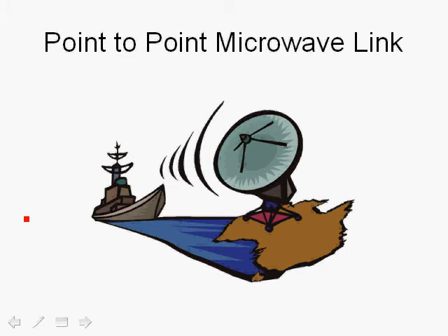When we design a digital communication link, we must specify a carrier frequency that is appropriate for the transmission of the information from terminal to terminal. For example, in satellite communication, we use microwave frequencies. The choice of carrier frequency governs the size of the antennas, for example. Certain frequencies have high attenuation due to atmospheric absorption. In general, we are restricted in many cases to frequencies allocated by regulatory organizations. At times, a carrier frequency is selected because a certain spectrum becomes available.